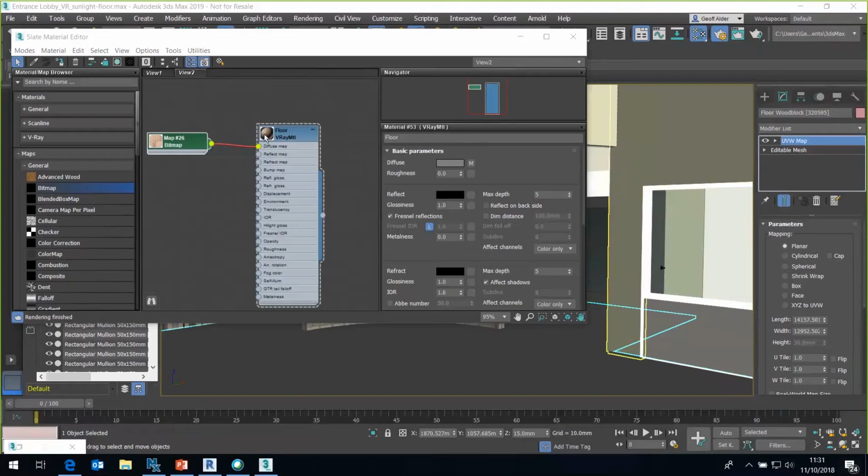And I tend to think about a lot of the maps, how big they are. A bit of a rule of thumb is that if I have maps that are 512 by 512, this particular map is actually 512 by 512. 512 by 512 pixels generally equates to a relatively nice render of a meter square or 800 to a meter. So what I'm going to do is change this map in here so that this length is, say, 800 and 800 and 800. So that gives me some mapping at 800 by 800.